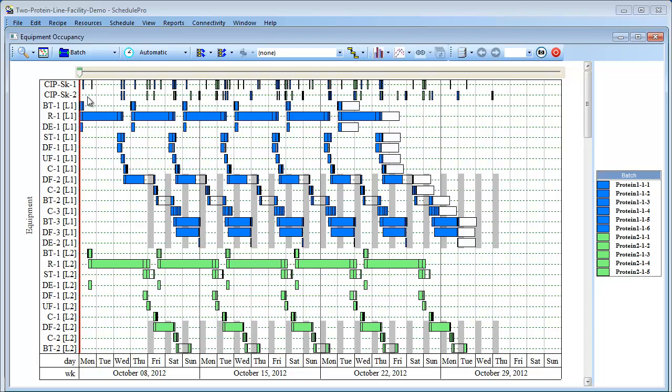Multi-batch campaigns can be scheduled based on their minimum batch cycle time or based on a larger cycle time with slack time between batches. In this example, there are approximately 12 hours of slack time between batches, which allows the plant to absorb some process variability. Note that the upstream suites in this example run 24 hours a day, 7 days a week.